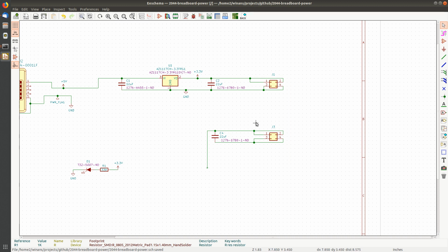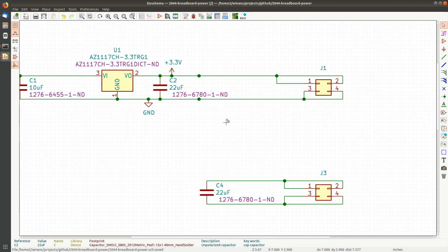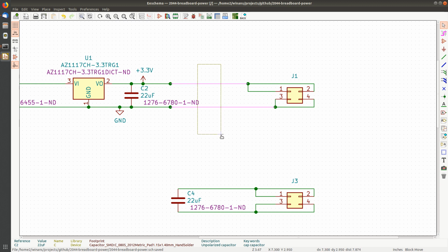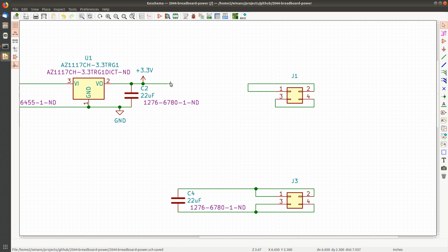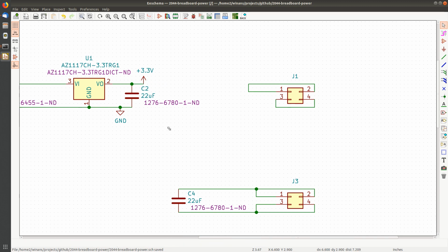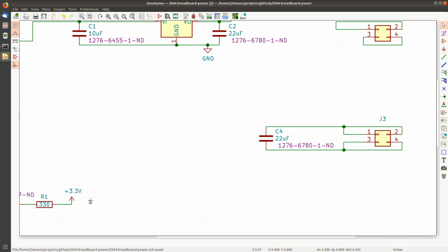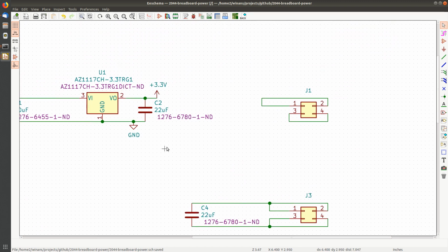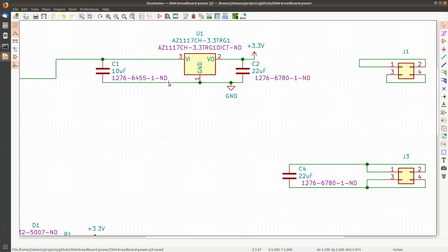So I'm going to remove those markings because they're no longer going to be fixed. No longer a fixed voltage. All right, I'm going to move this capacitor in a little bit closer. Okay. Now what I'm going to do is remove these traces. Delete. I'm going to hover over the end of this and hit delete. Hover over the end of that and hit delete, which probably would have been a cleaner way to deal with this mess I had a second ago down there. All right, so this regulator is going to sit on its own like this.